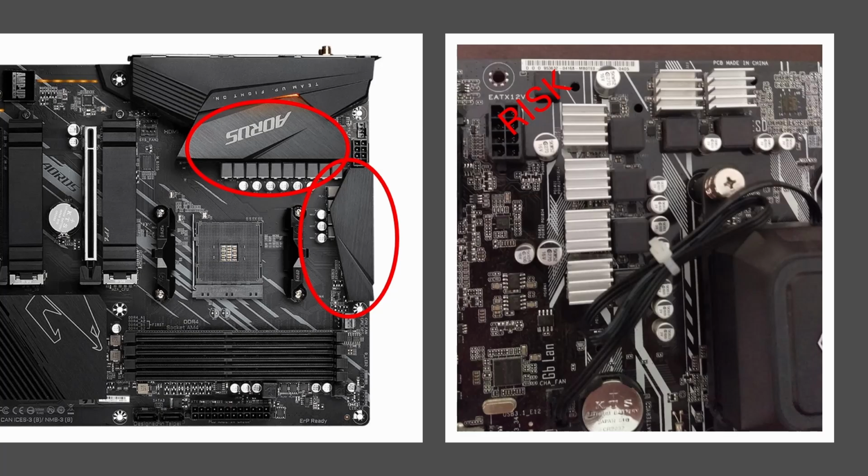Sometimes people will add heat sinks to their motherboard, as shown on the right. This can be risky, as these usually do not stick on that well. The thermal pad taping that is applied on these isn't designed to keep them installed onto the board. It's my recommendation that if you do try to use these, you have a secondary locking mechanism that prevents